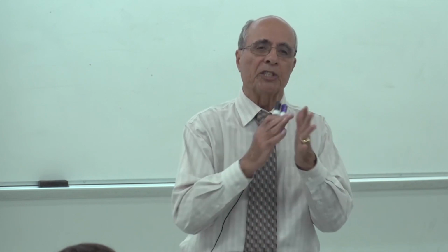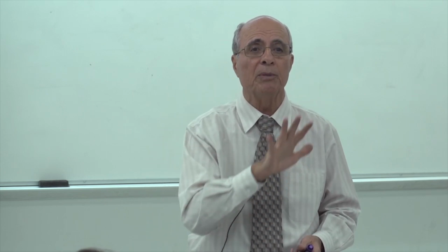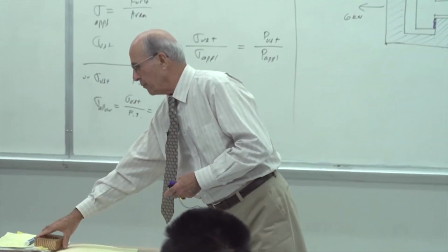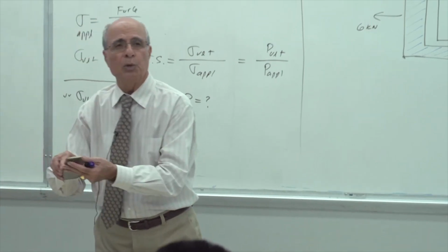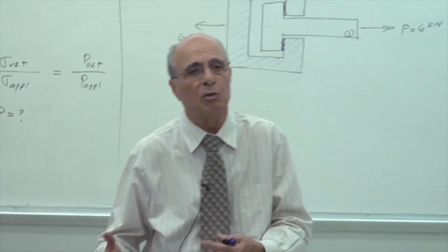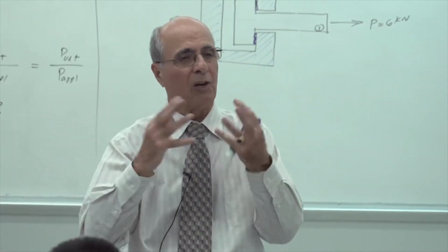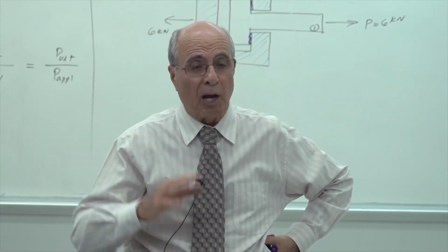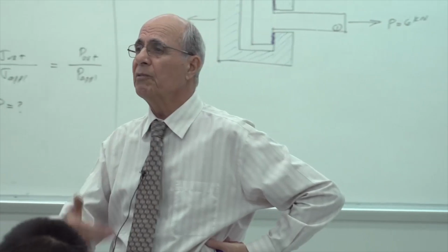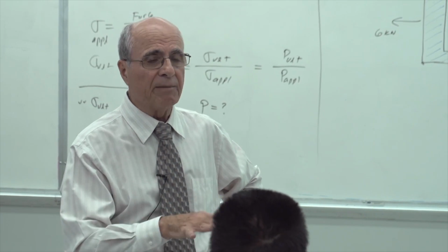That means it is on this total area. All the shear area for the time being is average because we are assuming it is uniformly distributed over the entire area. In other words, this is what we said last time too. If you have an area like this, you put glue here and you put it here, that area all being glue, we are assuming the shear is average. However, that could be not the case. Maybe in the corner it is less. Inside, we are going to talk about it again in chapter 6, how this is going to happen. There are changes or not. For the time being, we are talking about sigma average and tau average, uniformly distributed over the entire area. That's right. If there is any variation, we talk about that.